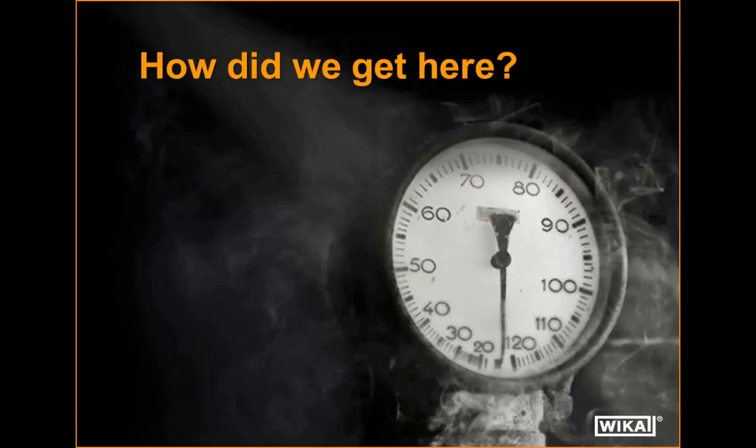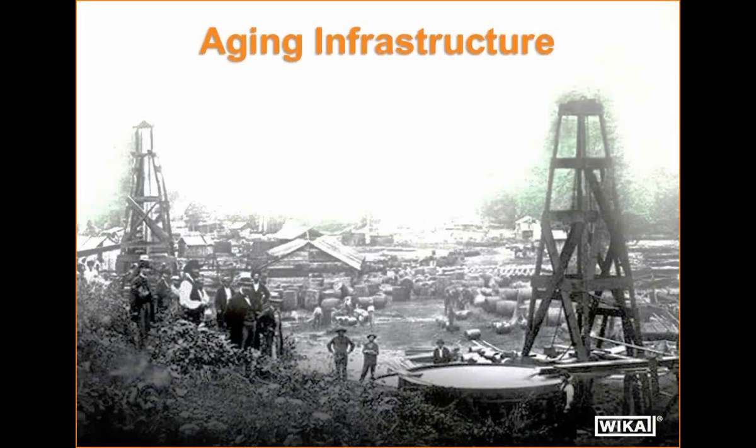So how did we get here? Why have gauges become such a mess in all of these plants? First, you've got aging infrastructure. As I said, these plants oftentimes are older than us. Numerous projects have been done to re-rate or repurpose existing units, but in many cases, the gauges weren't addressed as part of that project. You may have a gauge that was specified for a previous operating condition that doesn't even hold relevance anymore to the scale that it's now operating under.